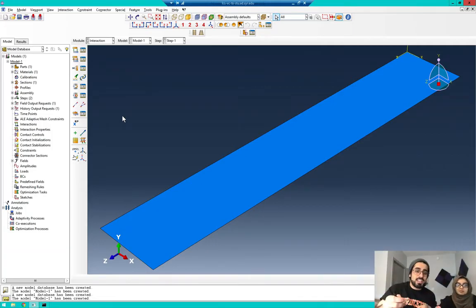So in Abaqus, we might have a local concentration problem, or stress concentration problem. To avoid that, I'm gonna tell Abaqus, for example, to link the deflection of this point here with the deflection of all of the points around it. So that not only that point is carrying all of the load, but the load is distributed to all of the points. Easy? Easy concept.